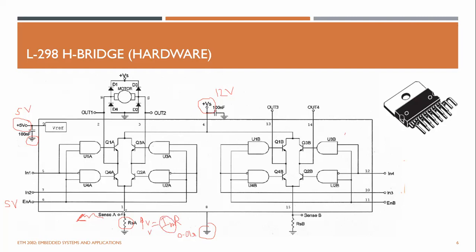So you can couple this voltage signal to the ADC channel of a microcontroller, and you can convert and find this voltage. And if you know the resistance, you can determine the amount of motor current, and that can be used for overload shutdown or any protection schemes, or sometimes to monitor the motor current for safety. And this is how you interface this motor.